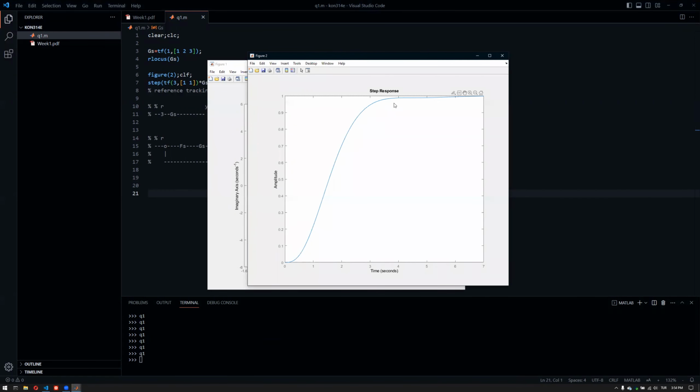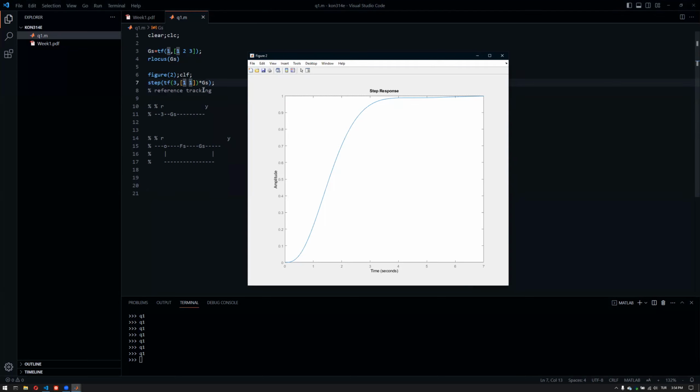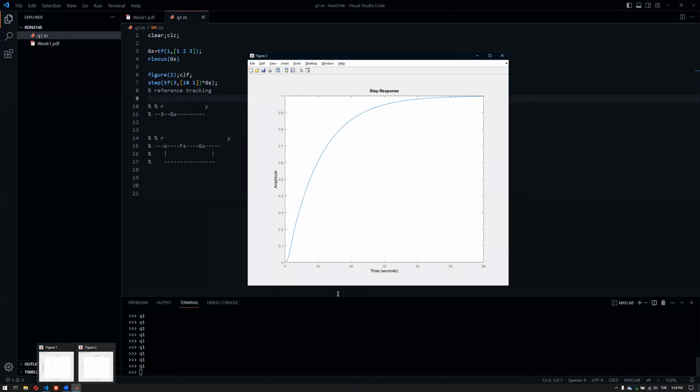Now you can see I eliminated, for example, the overshoot here. I could also improve on that. I can slow down the settling time here. So it's quite fast. But what I can do is, for example, choose, I guess 0.1. No, it should be 10. I could choose this controller as an open loop controller, and I'll get roughly 40 seconds of settling time. It takes more time, but it's slower. It could be used as a controller for certain systems.